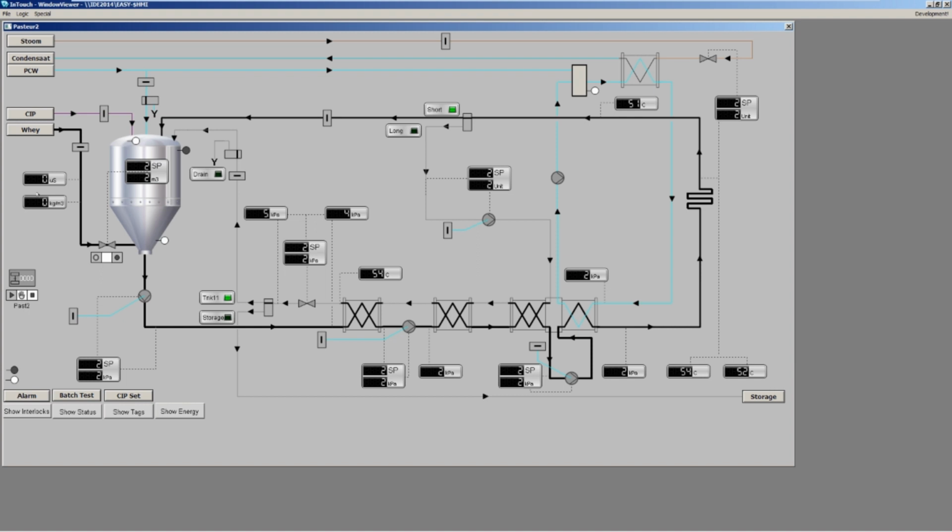In PLC Easy, the software modules like a valve is linked to a pump by using the 8 parameters, and by linking all these control modules together, they perform the cleaning in place functionality, the sequencing functionality, the group control functionality, the alarm management. In PLC Easy, this reduces the amount of software considerably, and at the same time, the software that is reduced is at the same time the most complex software that requires expertise. In PLC Easy, it's just like Lego bricks. We click the modules together, and by clicking it together, it gives me the functionality that I require.